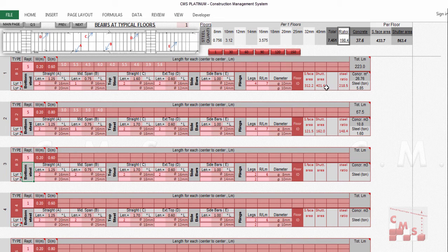The same we'll do for the other 5 floors, and you can also, as we said before, mention here the numbers of the floors which have the same code, the same description. Then you repeat it again for the next 5 floors with the other beams, even if you have B1 again, so you can put it here and put the length of the beams and description of the beams dimension and the reinforcement, as we mentioned before in the beam.